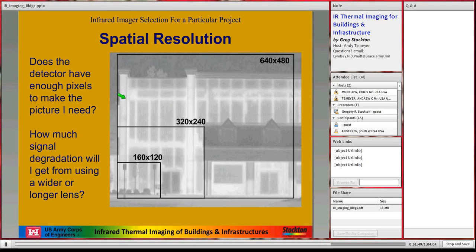But that doesn't make you an infrared thermographer. The point being that you should set aside 20% of whatever you're spending on the camera at least, and maybe more if you're buying a really cheap one, to get some training, because it's not as straightforward as it seems sometimes.